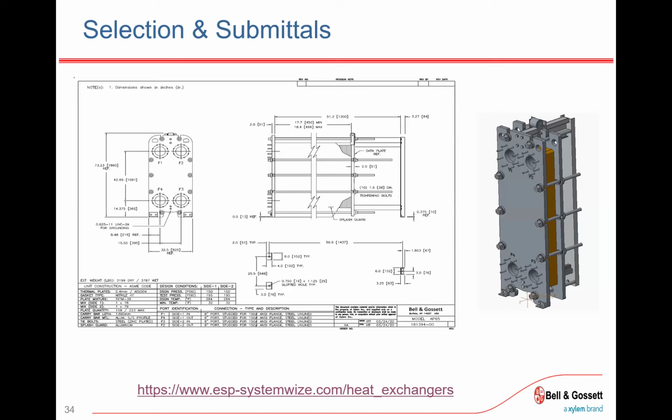If you wanted to do footprint or, let's say, floor space, you could filter by that. In this case, the lowest is 5.23, and that's actually the unit with the greatest efficiency. And we look at where we're at on the curve. You can select the curve. You see your best efficiency point is at 85. You're right there. That looks like a great selection.